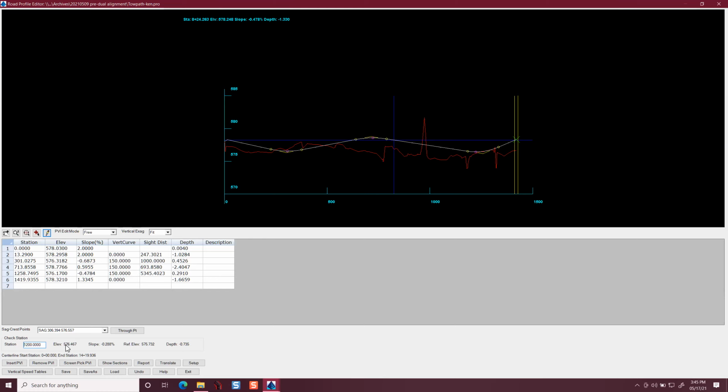I forget what we call the road, Towpath Road Main. Then we'd use that as the starting elevation for Towpath End, and make sure we set the end elevation of Towpath End to whatever that station value is, 637.35 or whatever, exactly as the end. And then that should make for a nice thing.